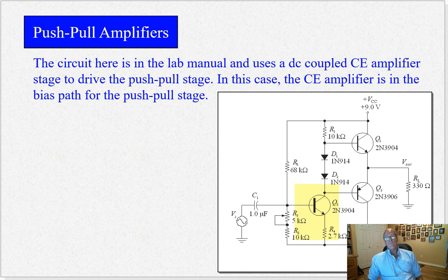So if you don't have matched diodes and transistors, what do you do? Well, you can put in this little bias tweaker circuit here, which is kind of cool. It actually replaces one of the diode dropping resistors in the circuit with this little transistor, the bias of which is adjusted with this potentiometer. Here we have a voltage divider bias on this transistor.